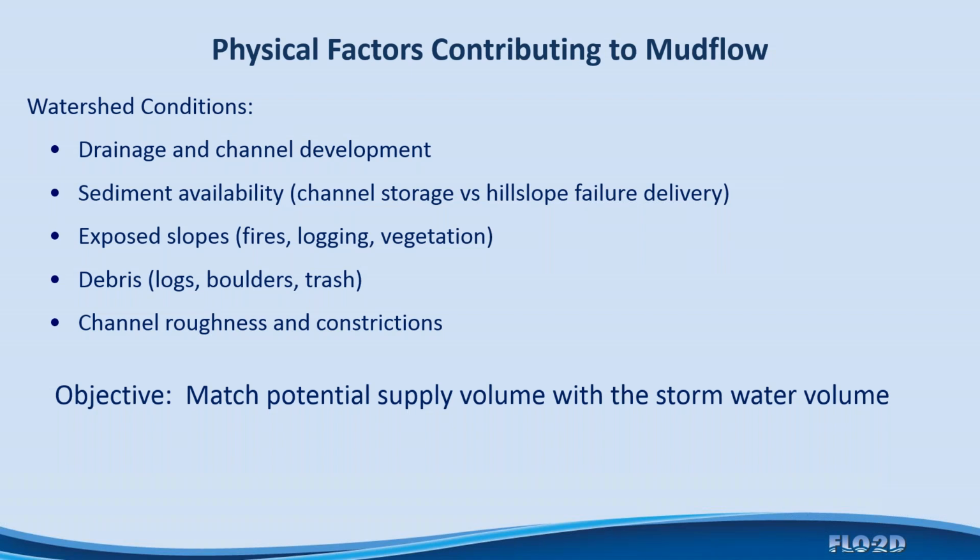So the thing that you should do if you're going to design some mitigation, prepare some hazard mapping, or maybe replicate an event, is to make sure that you understand what the watershed looks like under its existing conditions. That requires you not only to maybe sit in the office and look at aerial photographs or satellite imagery, but to get out into the basin and walk up and down it a little bit and understand what's going on, because what you want to see is how well developed the runoff will be.